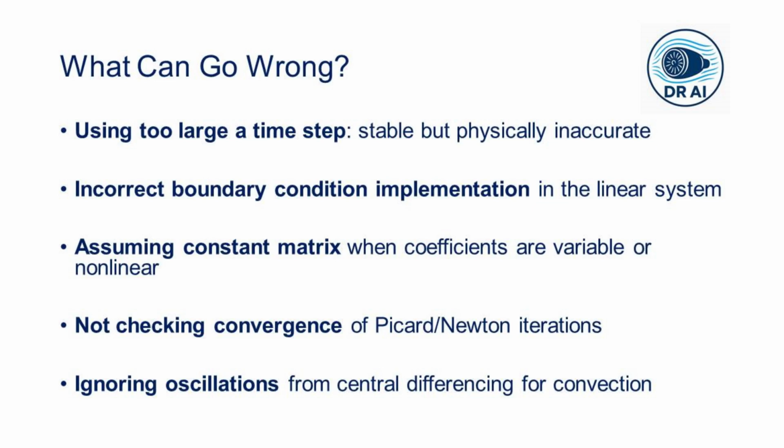The second pitfall is mishandling the boundary conditions in the implicit system. When you modify the matrix to enforce Dirichlet type boundary conditions, it's very easy to forget to adjust the right hand side correctly. A simple debugging technique is to compare the numerical solution against an analytical solution for a simple case such as a sinusoidal initial condition with known exponential decay.